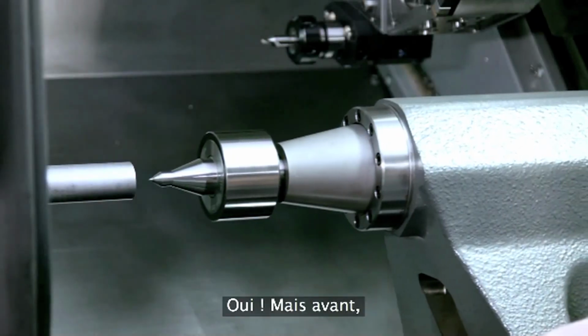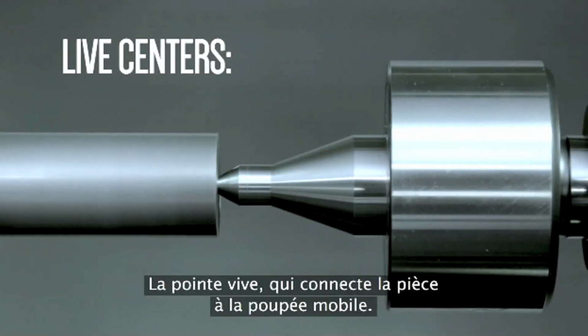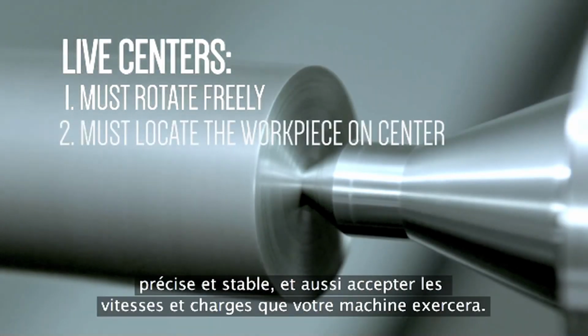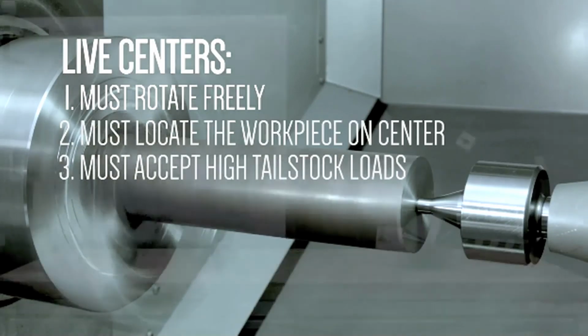Okay, so can we run our part already? Yes, but before we do, there's one more thing to consider. The live center. This connects the part to the tailstock. It must rotate freely. It must locate the workpiece precisely and rigidly on center, and it must accept the speeds and loads your machine will exert.